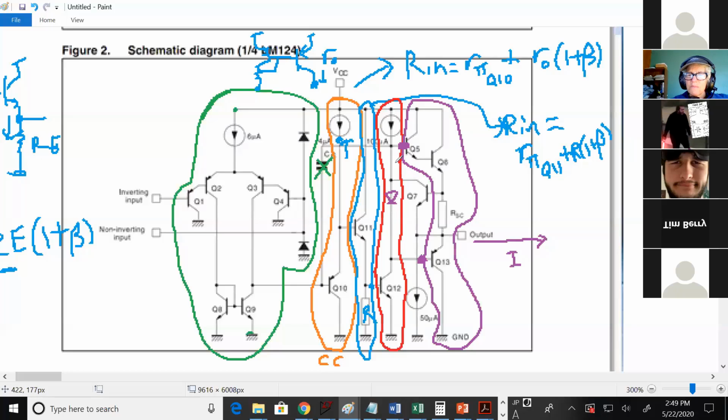I'm not sure whether it's better to go above here. I don't think it matters. If when you're working, you actually build this circuit and the diodes don't go here, don't come back and get mad at me. Okay, yeah, so like 3 diodes there. Now we've got 3 VBE on between the 2 bases, and we've got rid of the crossover distortion.